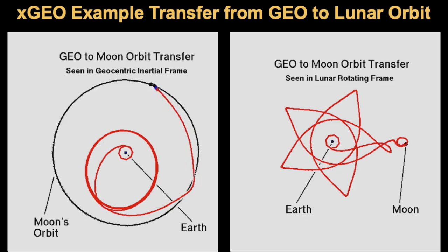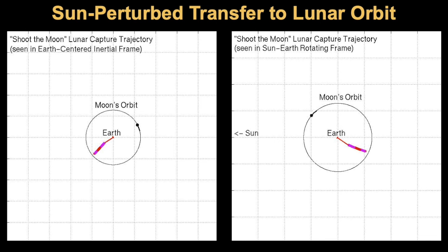And I'm going to revisit this several times because it has a bunch of different ingredients. This multi-pointed star shape represents a mean motion resonance, but as seen in a rotating frame. And then these libration-point dynamics get involved, even though we're not necessarily getting onto a halo orbit or a Lyapunov orbit or other orbits that maybe you have or have not heard about.